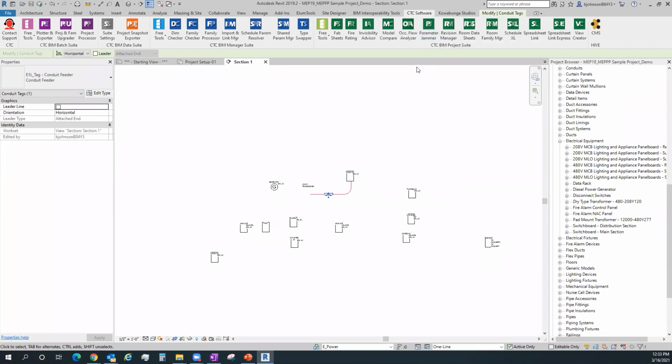The other side of that is if you are working with, say, entire libraries of content and you want them to work similarly, again, the right parameter for the tag has to be in there. If you downloaded an entire library of, I don't know, say light fixtures or something, and you want every single light fixture in your one line, you could go into the thing called Family Processor, which is a way to basically fix families that you get from outside your firm typically.